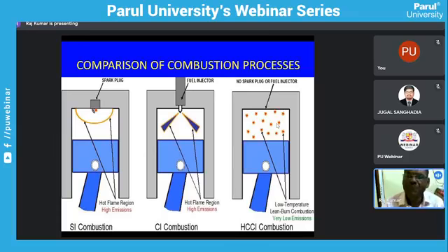The compressed air may be drawn from the turbocharger. The compressed air is available, and the fuel is also injected as per the requirement. So there, the mixture is prepared inside the induction manifold. Now that mixture is going to the combustion chamber. If the quantity of that mixture can be controlled as per the various speeds of the engine, we can control the output of the engine. So the efficient firing will take place.